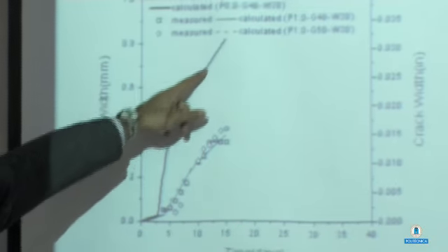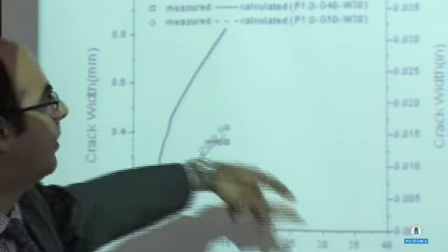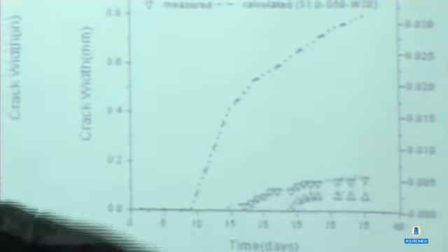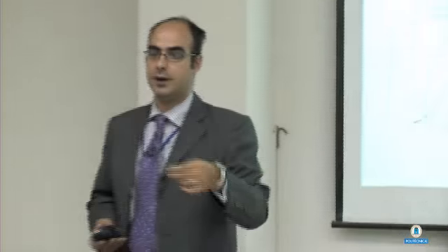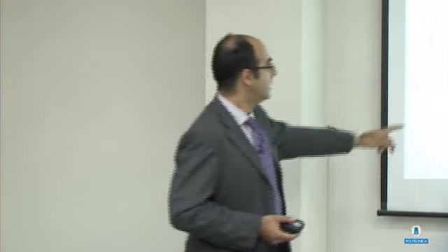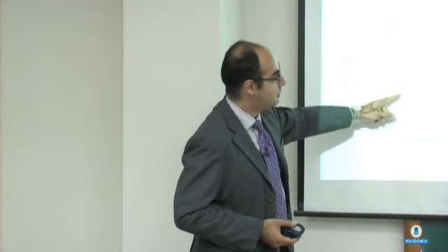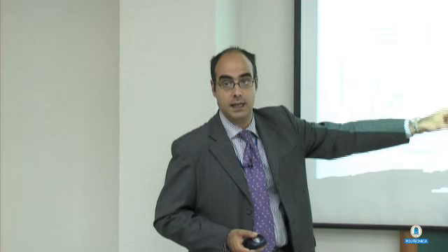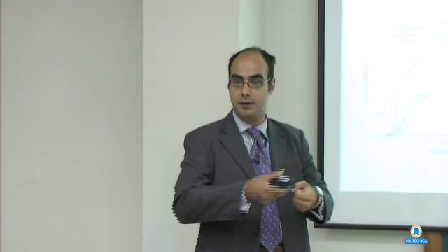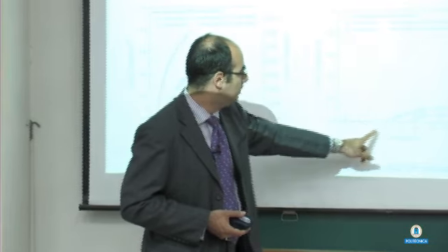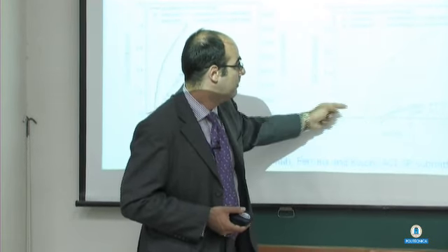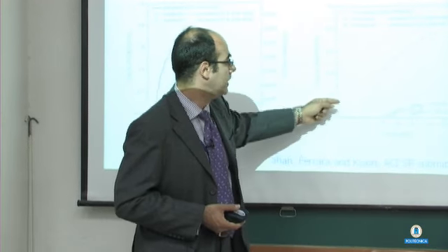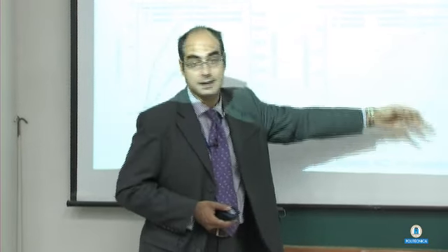This is the plain matrix for polypropylene fibers. This is the plain matrix for steel fibers. They were different because of the different geometrical properties of the fibers. And you can see, both with polypropylene, but most of all with steel, which is more effective, probably because it has a better bond and the final hook is better, you have a great improvement in the performance. The age of first cracking is surely delayed, but the final crack opening is dramatically reduced,